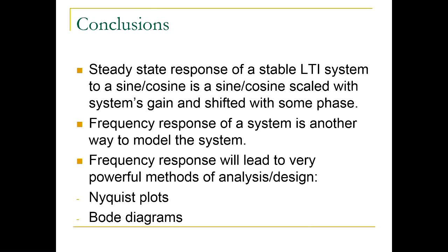Right? All right, so what to take from this lecture? The steady state response of a stable causal linear time invariant system would be a sinusoidal signal at the same frequency as the input frequency, with different amplitude and different phase, right? So we then could introduce this frequency response. Actually, frequency response is a different way to model the system. We started off modeling systems with differential equations, right? From first principles we got models, from Newton's laws of motion, things like that.